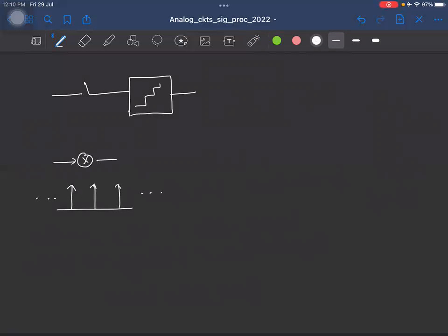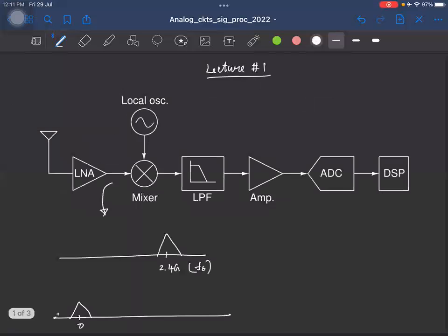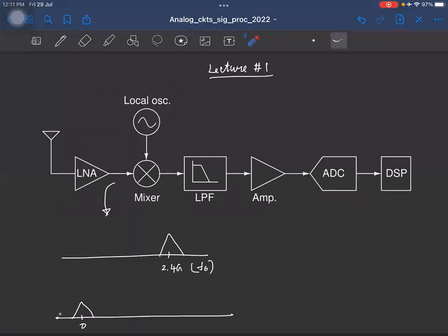Right? So again, you have a similar scenario where the input seems to be multiplied by a periodic signal, right? So what kind of system is this? Again, it's LPTV, right? It's linear, periodically time varying. Is that clear? So even our ADC is an LPTV system. Okay, and not just these two blocks. There are several other blocks which are not shown here for simplicity, which are LPTV systems in this receiver chain.